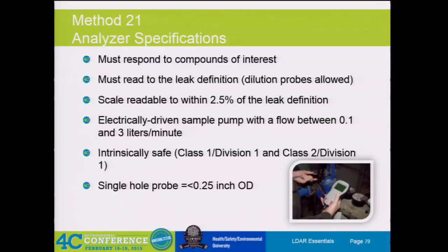As you guys all know, when you get certification cal gases, if you read the pieces, it says plus or minus 2%. That's where this came into play, so that when you're calibrating it, the gases are going to be within this, so the analyzer will read within the requirement of this reference.